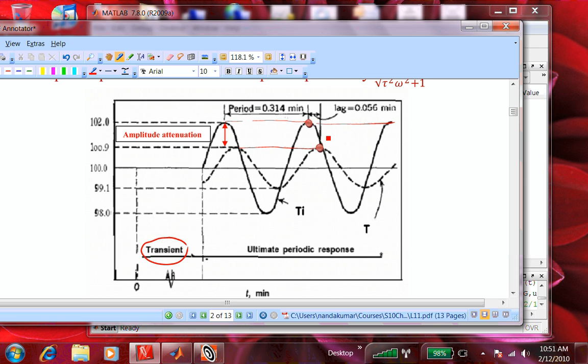In fact, in Canada, I guess it is important to take into account the variation in the temperature in designing how deep you should bury the pipeline so that the water doesn't freeze. So I give as a problem in the heat transfer course, where you have to look at the transient heat convection from the surface of the earth into the ground, where the surface temperature is changed periodically. And you need to know below what depth the temperature will not go below 32 degrees, so that you bury the pipe that deep.